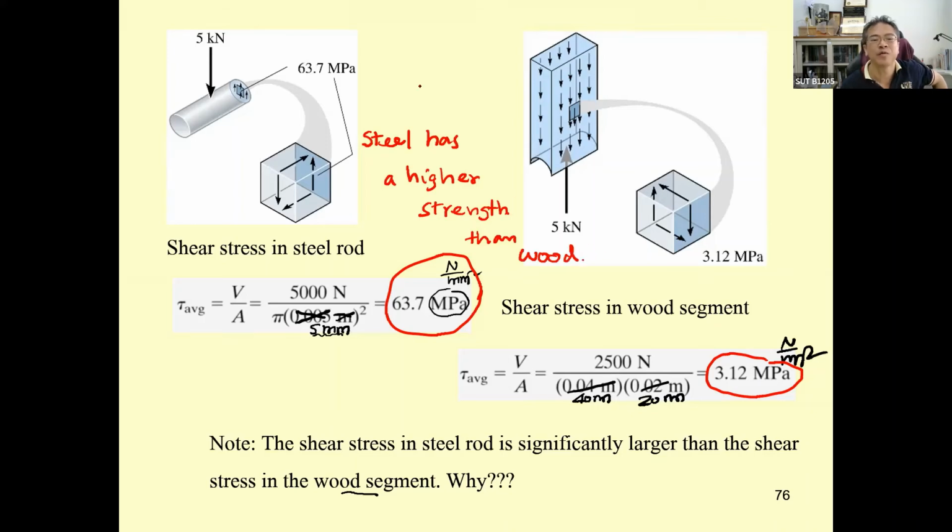Usually when we measure this, we use the sigma sub y to represent the normal stress, the strength for the tension or compression of the steel. We use the tau sub y to represent the shear strength. Usually, tau sub y for the steel is going to be 120 megapascal. But tau, the strength of the wood, I just call it tau sub PL.